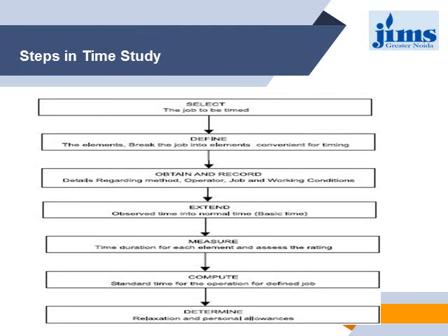The basic steps in time study. Observe time and apply the rating factor to obtain the normal time for every element. Add the suitable allowances to compensate for fatigue, personal needs, contingencies, etc. to give the standard time for every element. Now compute the allowed time for the entire job by adding elemental standard times, considering the frequency of occurrence of every element. Make a detailed job description describing the method for which the standard time is established. Test and review standards.